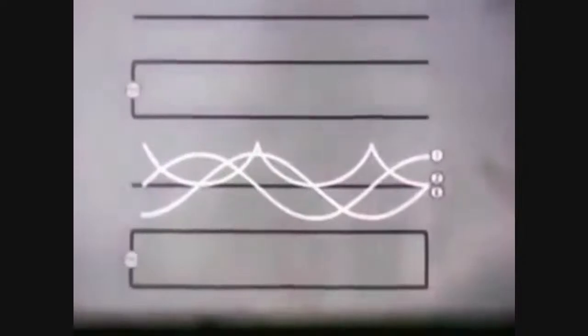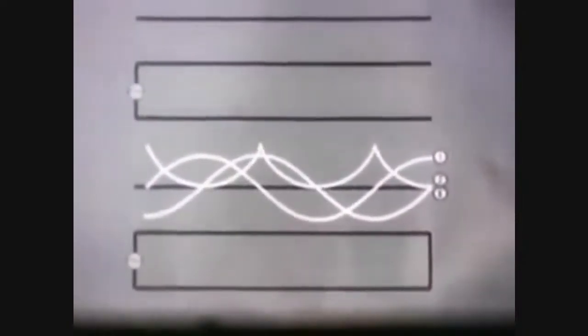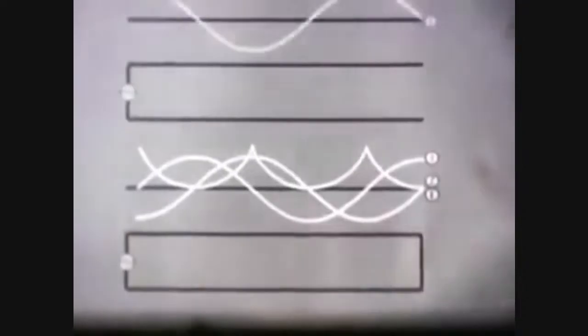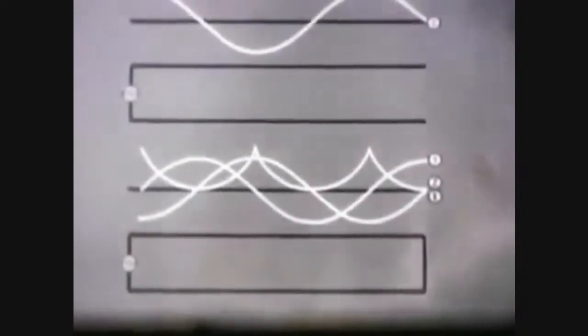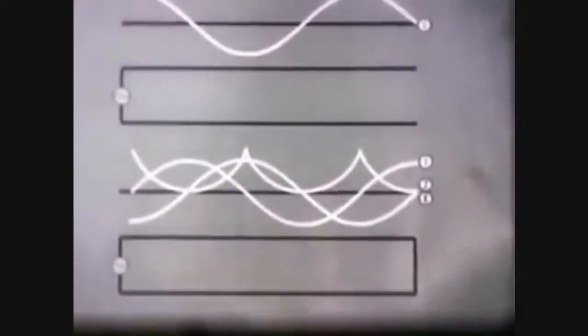According to Ohm's law, when current is maximum and voltage minimum, the impedance is minimum. In the case of an open-ended transmission line, we find an immediate difference in the current curve. There is no current flow at the open ends of the line. Therefore, the current curve is at low point here.